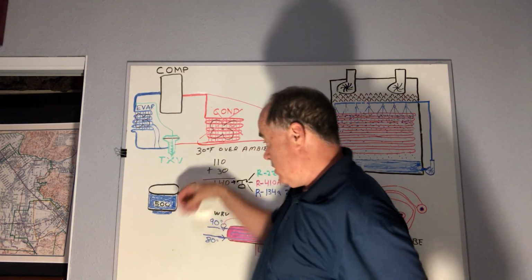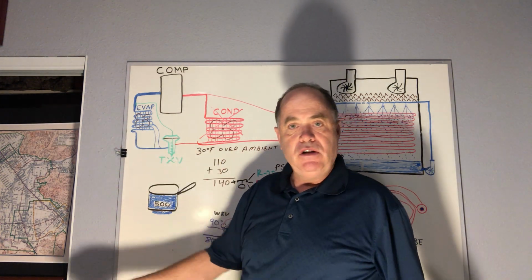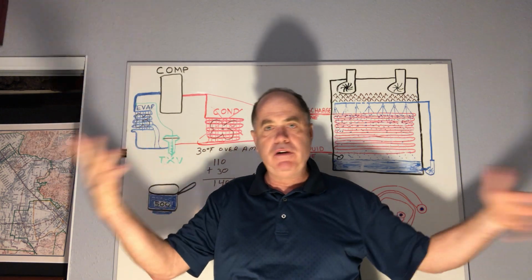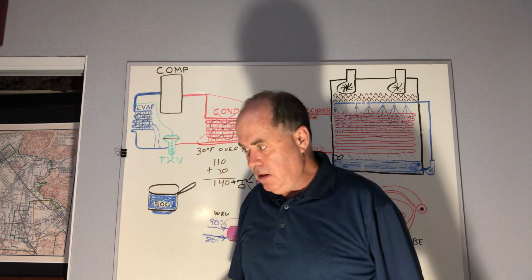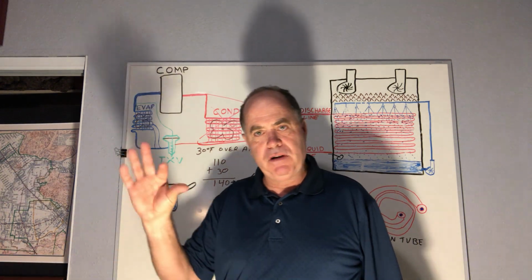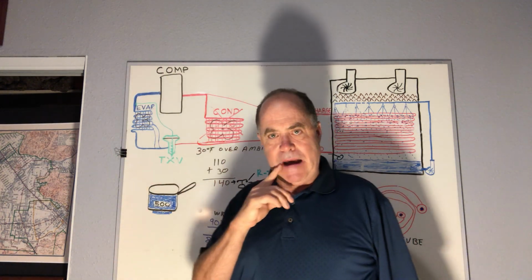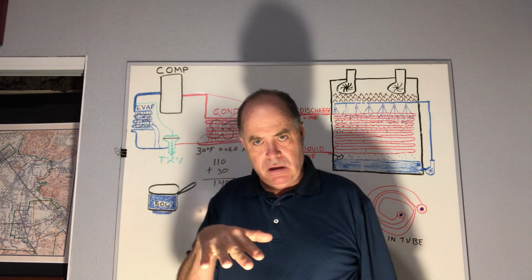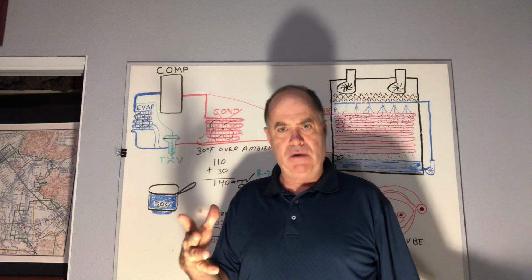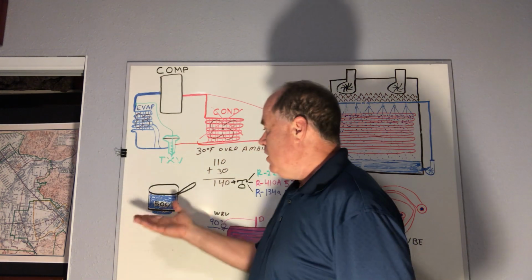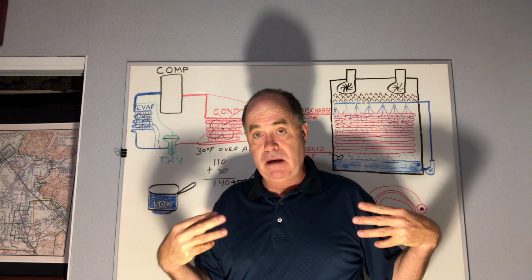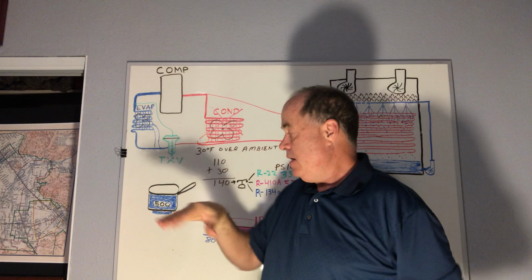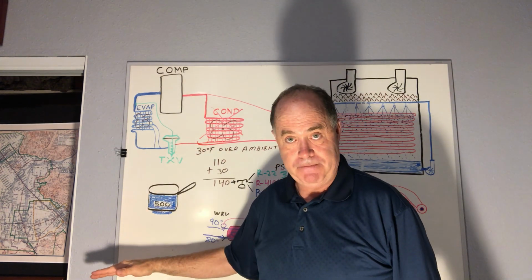Have you ever had a pot on a stove full of water and you boiled it and then life got busy and 3 or 4 days went by and you finally got some time off work and you look in the bottom of the pan that had been sitting there with a little bit of water in it and all the water has evaporated and there's a little bit of white powder at the bottom of the pan? You're like, how is this possible? Well, the water evaporated and the minerals that are coming in with the city water all the time, they don't fly up into the air. The rocks and the minerals and the calcium carbonate, they stay behind and they concentrate, okay?